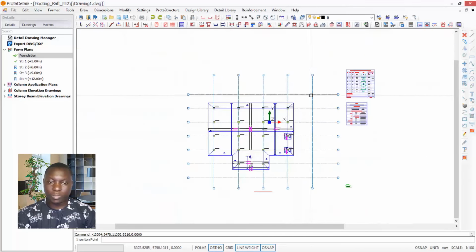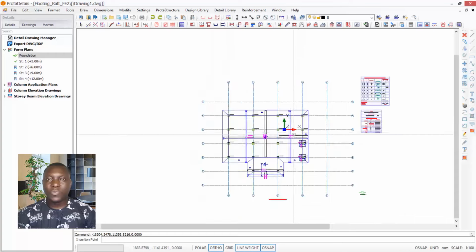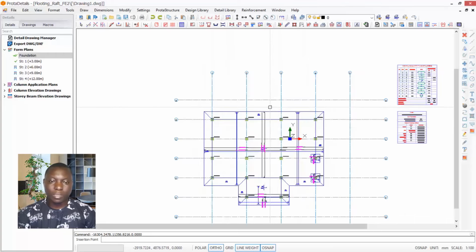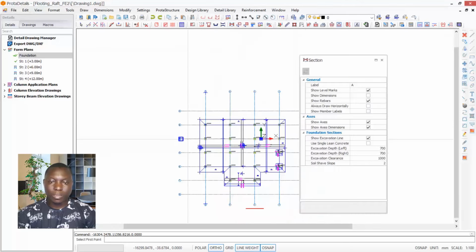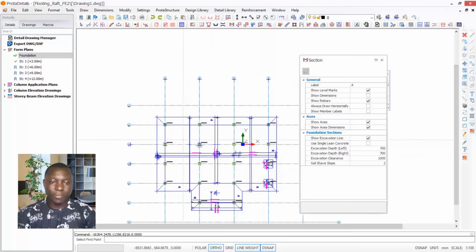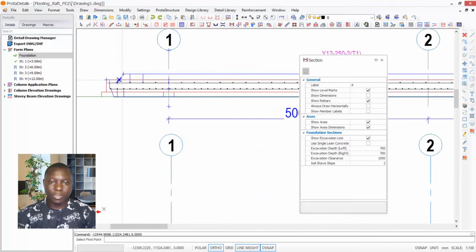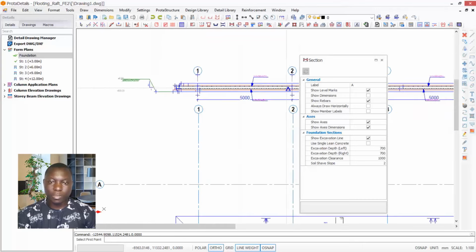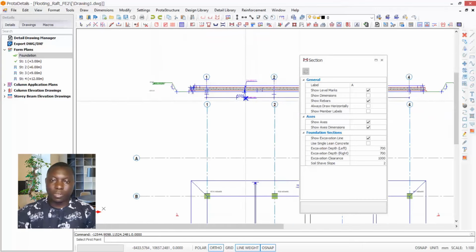So what I just need to do here is to cut the sections before I can take it to AutoCAD. To cut the sections, you can pick from here. Then you have to pick the 2 points. First point, turn on the auto to have a straight line, and second point. So this is going to cut the sections just like this for you, and then you place it right here. Zoom close, you can see the sections right here. All right, so having done that,